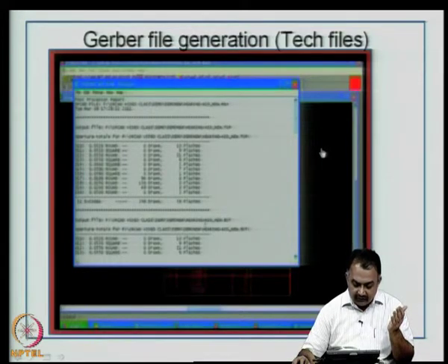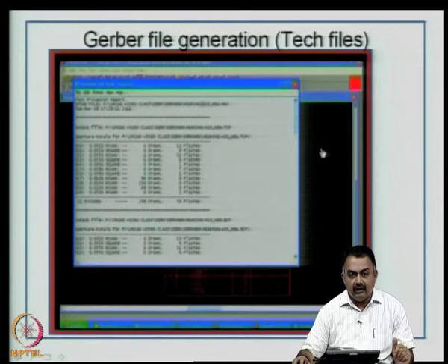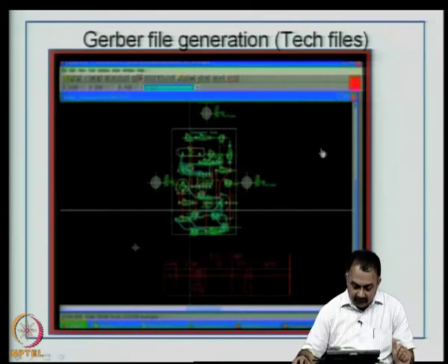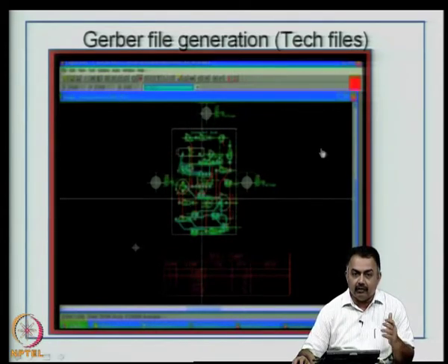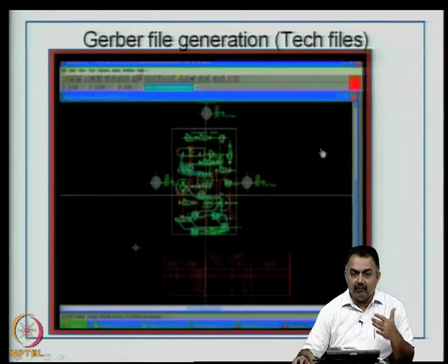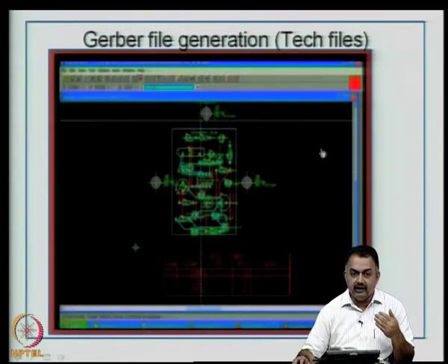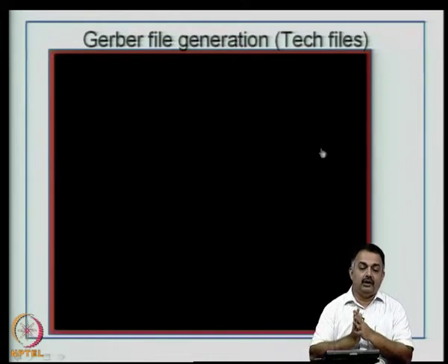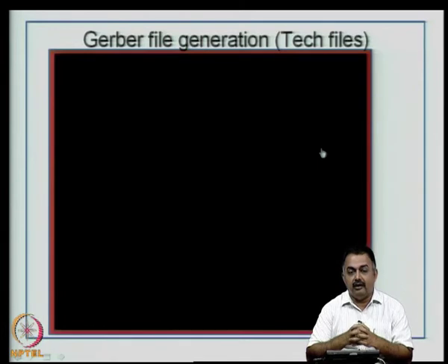Then after this, you can also create a drill file. So, drill file is based on Excellon format, and in a drill file typically you will see XY coordinates of the drill mentioned, the number of drill bits used and the sizes of each of the drill bits used, including the vias and the pads and so on. So, this is a very good documentation that you have to correctly generate before you send it off by electronic means to the manufacturer.